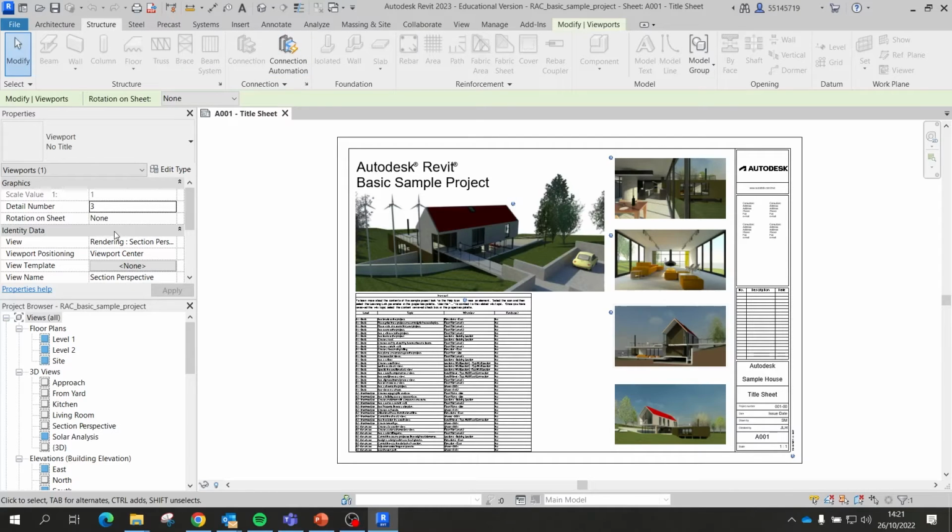I'm going to open one plan. Where do I find the drawings that are currently in my project? If you look down here, there is one thing called Project Browser. This is the Project Browser. And you see in blue, checked in blue, all the drawings that are currently somehow present in the boards, right? They are used in the boards. Not necessarily in this board, but on another one. This is the main navigator for you. This is the main way for you to navigate inside the project.